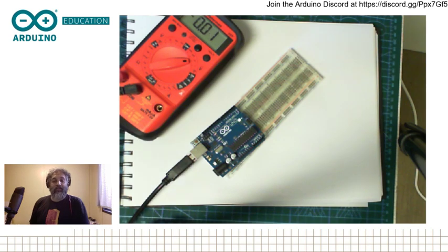Of course, if you build a system with a motor and you want to understand how much current the motor is consuming, you can always put the multimeter on the way. But it's really hard to cut a digital circuit somewhere to just put a multimeter in the way to measure where the current flows or not. So you need to focus on measuring voltages.